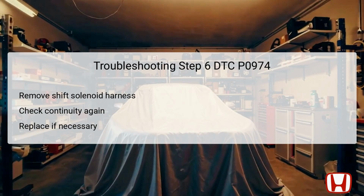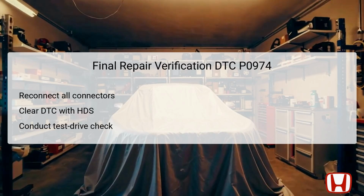On the other hand, if continuity fails, this implies that the shift solenoid wire harness itself is faulty, necessitating its replacement. By systematically following these steps, you can effectively isolate and address the cause of the DTC P0974. The final verification step is crucial to ensure that all repairs have been effective and that the DTC P0974 has been addressed correctly.